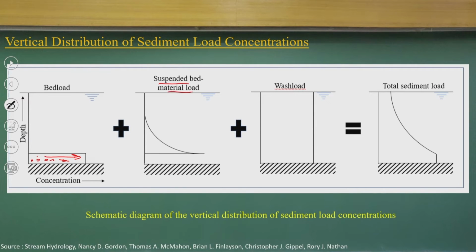All these bed materials go as suspended load, and they remain in suspension because of turbulence lift and also the buoyancy forces, both lifting the suspended particles, which will be exponentially decayed as we go from the bed to the free surface.